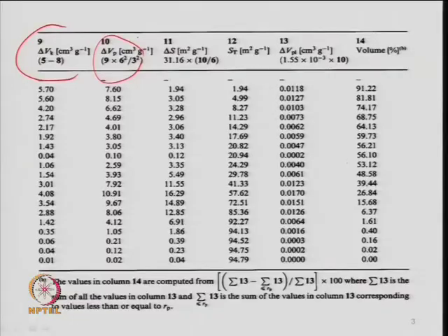This can be related to your pore volume, because I told you that pore volume is related to the pore radius. So, delta V_p upon delta V_k is equal to r_p upon r_k whole square. Delta V_p is nothing but the volume of the pore, that is, cross-section area of the pore into length. So, pi r square multiplied by length. The length of the pore is the same, so you can very easily correlate delta V_p and delta V_k, which is given here by multiplying by the square of the radius, that is r_p over r_k whole square.